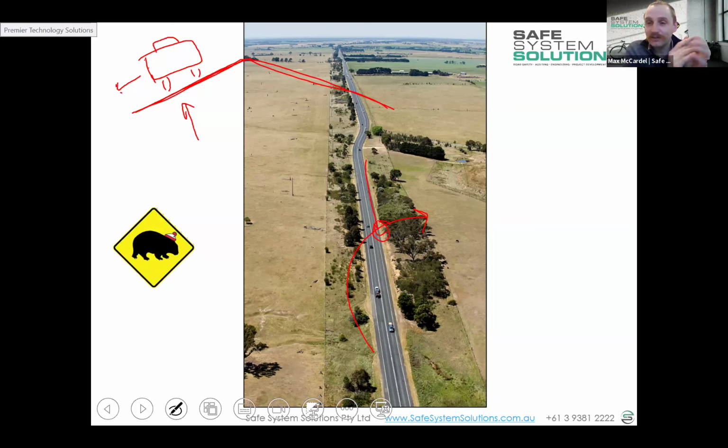Just something to be mindful of. If there's no separation between those traffic streams, those types of crashes still can occur and do occur quite commonly. But of course, we need to be considerate of the adjacent roadside and trees. There are single point source hazards, as well as utility poles, just every 40 meters or whatever. They are just point impact hazards for motorists,